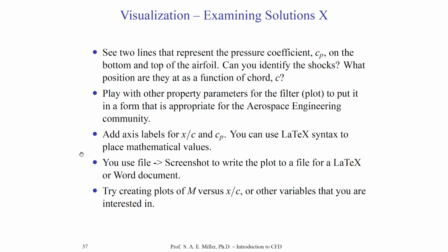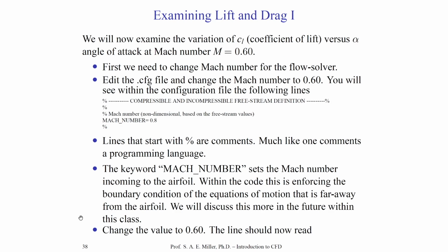You can then, of course, make screenshots to make the files and paste them in Word documents if you're making a report, or better yet, a LaTeX document if you're preferring something more professional. And of course, you can write them as EPS or vector graphics through the system file commands. I recommend making vector graphics for line plots and not sloppy JPEGs, which have lossy format for plotting. Anyway, try on your own creating a Mach number versus x over c plot or any other variables you're interested in. Let's now turn our attention to examining lift and drag.